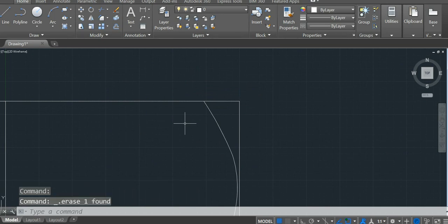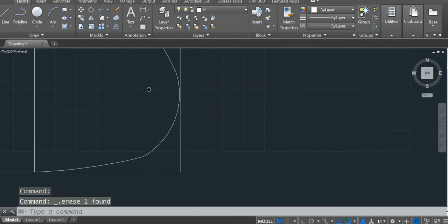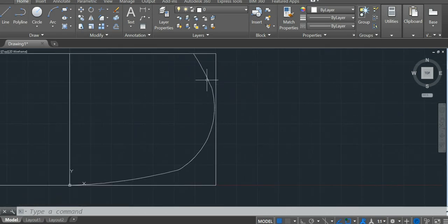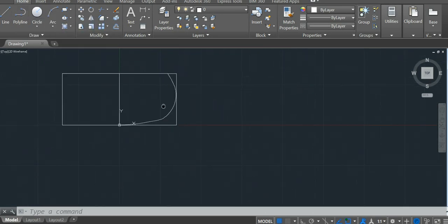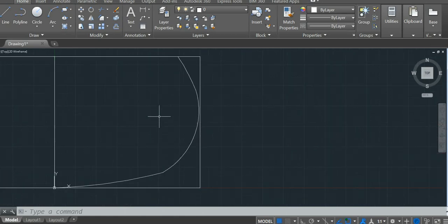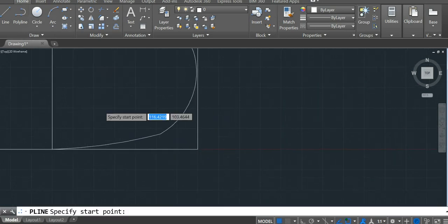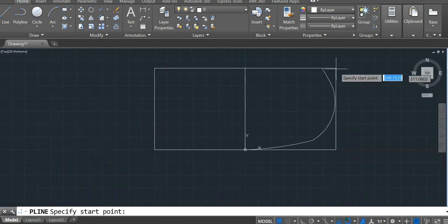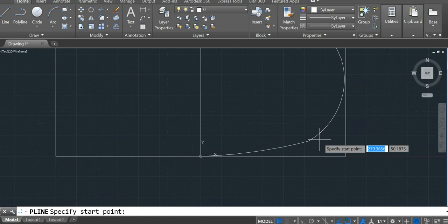You can just click a line and press the delete command to get rid of it as well. Anyway, so play around, find a different shape. But if you use the arc tool or the circle tool, to get the coordinate points of the ends, it'll only give you a couple of coordinates, because what we're going to be doing is getting all the points that make up this line. So it's really important that you go in with the polyline tool and try to stay as close as possible to the smooth line you've drawn with the nice arc shapes and the circles.